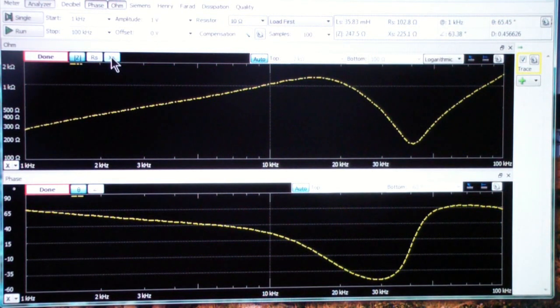This is the actual impedance, and we'll be talking more about this because somebody asked a question about whether you can use a power transformer as an output transformer for a tube circuit, and the answer is, like most things in life, it depends. It depends on the turns ratio of the transformer, the core material, how the windings are put on it, and so on. The short answer is yes, you can use it, but you may not get very good performance.